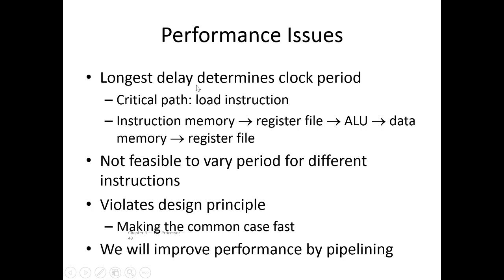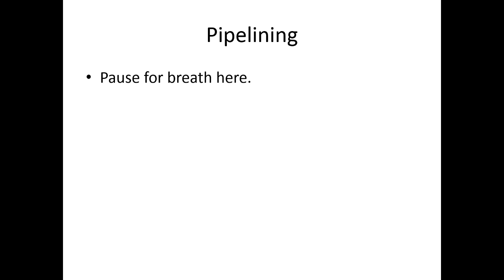So I already mentioned this. Theoretically, your longest delay in that path is going to determine your clock period. Okay. There's different methodologies on this, but essentially we want to make the common case fast and not violate the design principle. Okay. We can improve this later by pipelining.